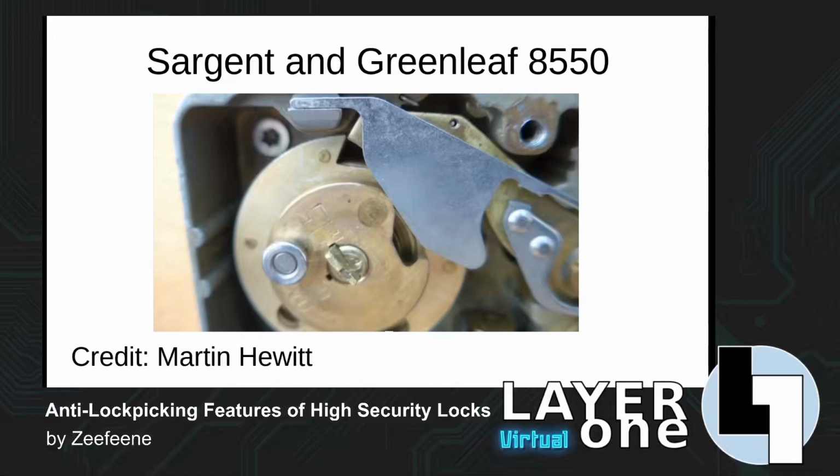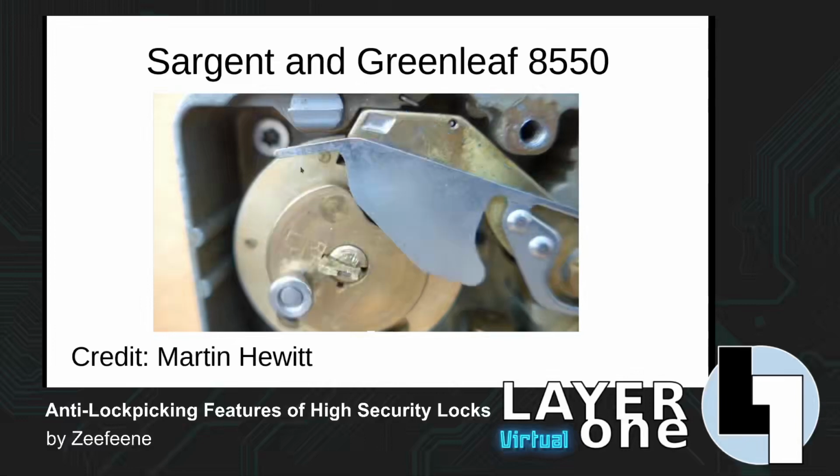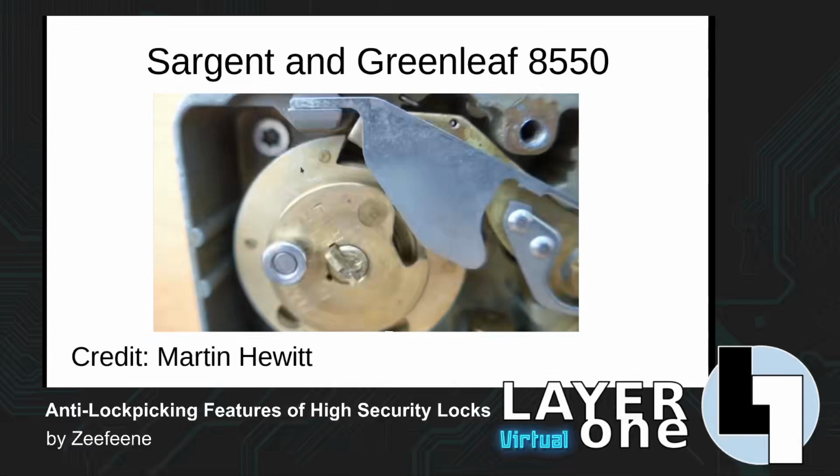And what that does is it basically stores a lot of kinetic energy in this kind of spring, and the drive cam itself can actually move front to back, so kind of depth-wise as we look into the picture, and that means that the mechanism can be released.